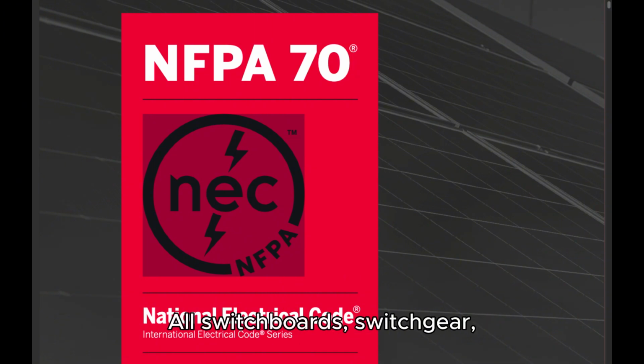E. Dedicated equipment space. All switchboards, switchgear, panelboards, and motor control centers shall be located in dedicated spaces and protected from damage. Exception: Control equipment that by its very nature or because of other rules of the Code must be adjacent to or within sight of its operating machinery shall be permitted in those locations.